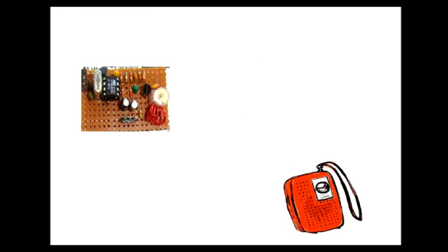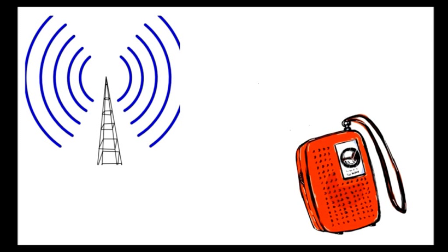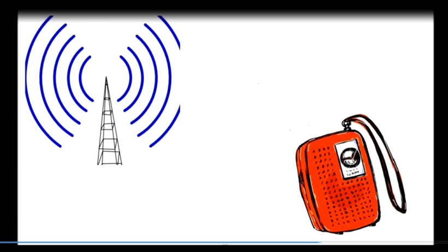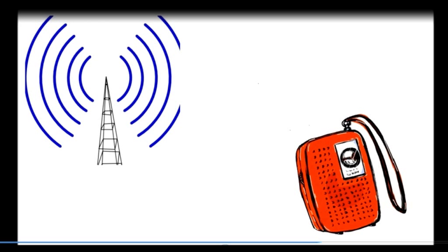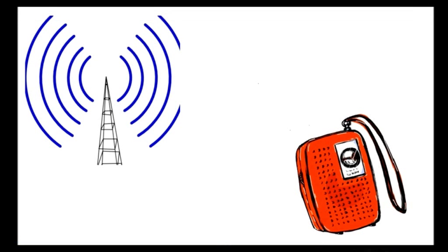When you adjust the tuner wheel of an FM radio, you vary the capacitance of the circuit inside the radio. By doing this, the resonant frequency of the circuit changes, such that the resonant frequency of the circuit becomes nearly equal to the frequency of the radio signal received. When this happens, the amplitude of the current with the frequency of the particular radio station in the circuit is maximum and the sound of the desired radio station is maximum, and thus we simply listen to the desired station leaving out the others. And this is how a radio works.